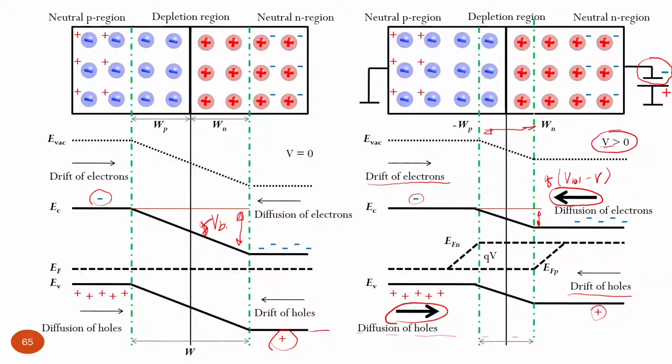If we inject charge carriers, it means we are out of equilibrium condition. So far, when we had no bias, we had one single flat Fermi energy level, which corresponds to thermal equilibrium for all systems. Now we start to inject a lot of minority charge carriers in opposite regions, and obviously it's not equilibrium condition.